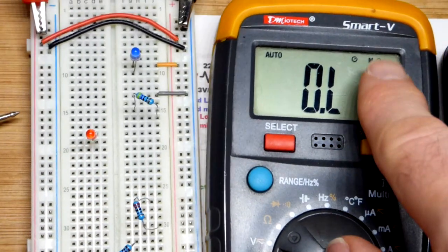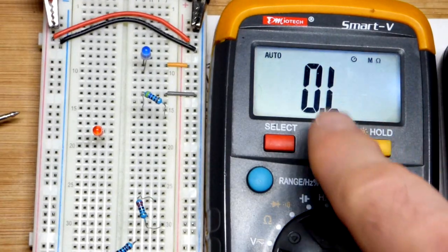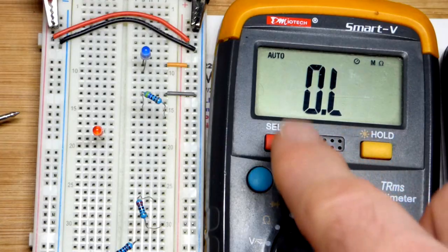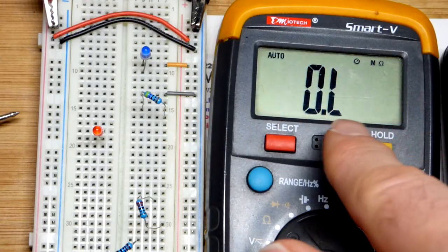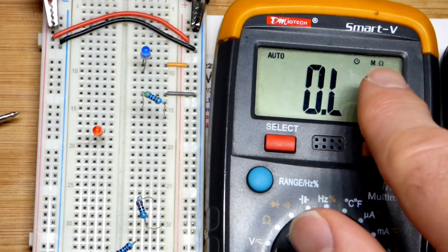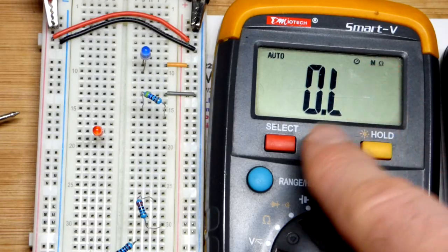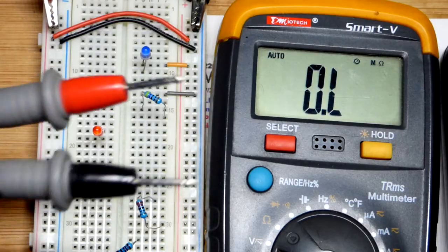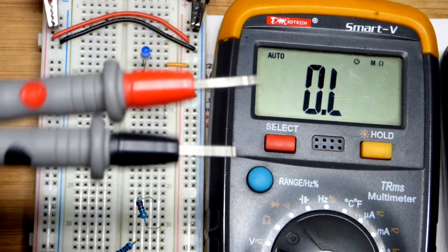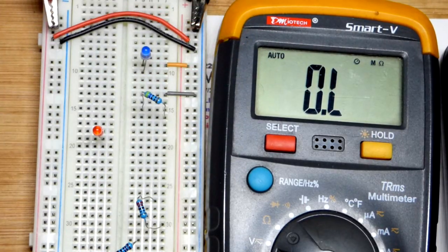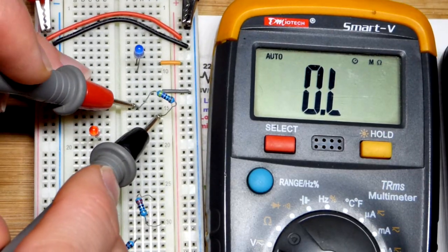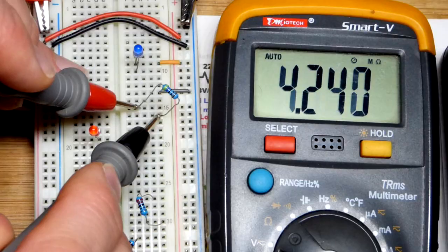And so yeah, it can show even in the millions of ohms. I think this goes up to somewhere around 200 million ohms. Million ohms, not milliohms, 200 million ohms. Having trouble saying that for some reason. In any case, that's mega for millions. It's out of limit though. There's more than, I think, 200 million ohms of resistance between these two probes. So we just go to it. It doesn't matter which side you put the probe, just touch the wire leads right there.